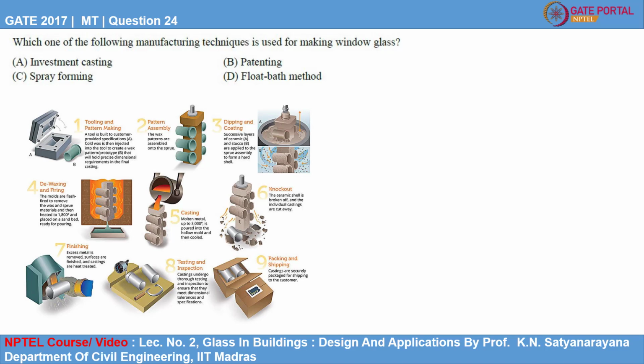So the third option is spray forming. In spray forming, an alloy is melted normally in an induction furnace, and then the molten metal is slowly poured through a conical tundish into a small bore ceramic nozzle. The molten metal exits the furnace as a thin free falling stream and is broken up into droplets by an annular array of gas jets.